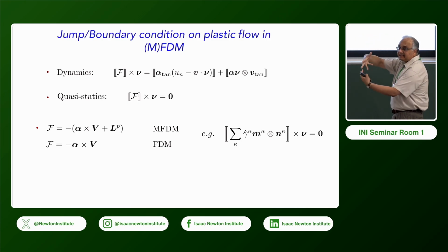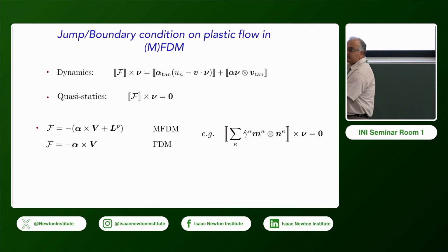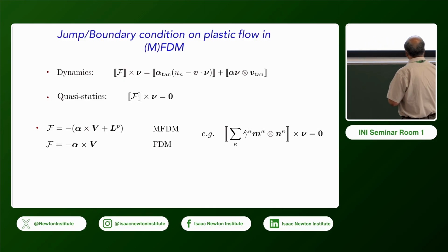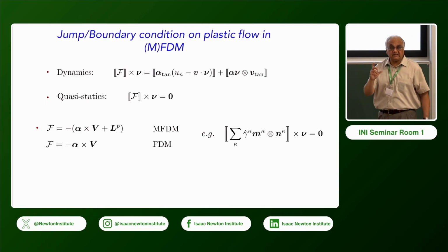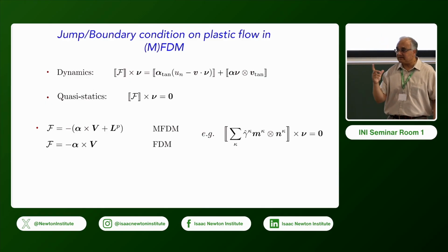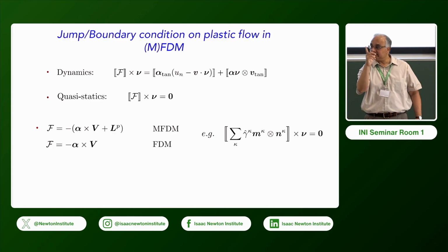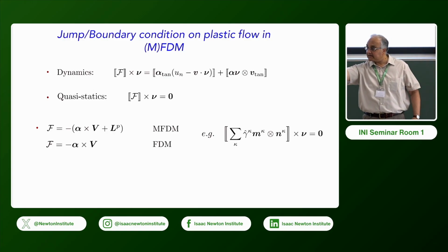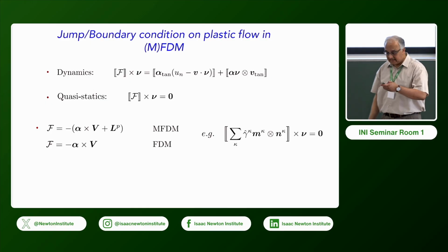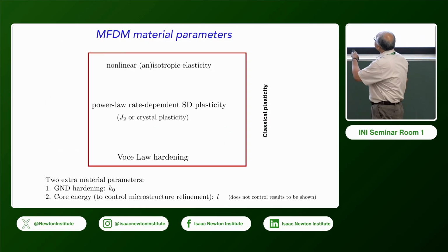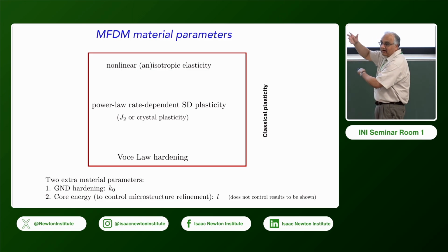So this says that across a grain boundary, the two crystals have to talk. And if there's a plastic strain rate there, the classical crystal plasticity strain rate, this jump condition actually depends on all 5 grain boundary parameters: the misorientation across a grain boundary and the 2 parameters characterizing the orientation of the grain boundary. It shows up in the theory. So this is classical plasticity for the LP part, which we are going to phenomenologically assume.